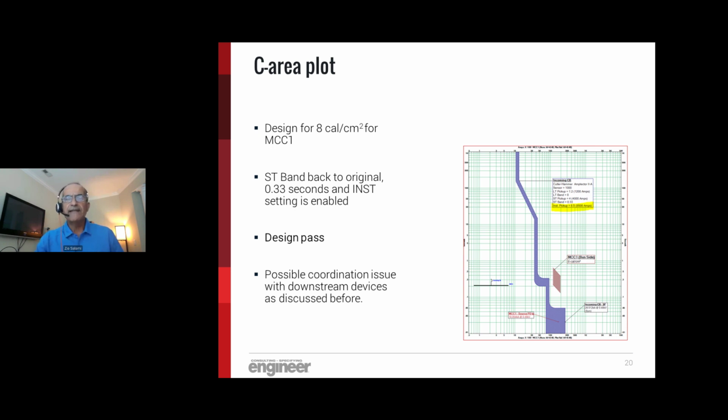That tells us that at any time, with all the variation that we are involved with performing the arc flash, those variations that I already pointed out, we are guaranteed that we will be below 8. Actually, in this case, probably much more than below 8 in some cases, and therefore that will be eliminating a lot of runs because we just have, based on what we did, based on these settings, and this is guaranteed, again, based on the minimum and maximum short circuit, available short circuit at the facility, based on voltage tolerance, and based on other tolerances, as you saw in the clip, that is part of the arc flash study.